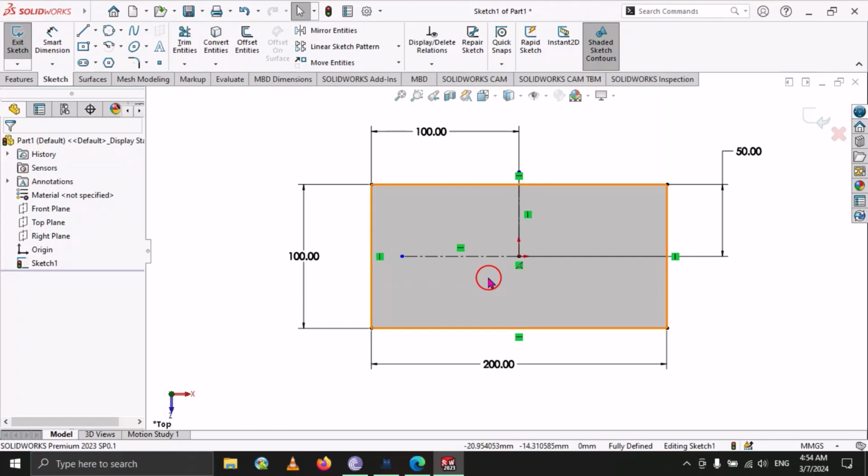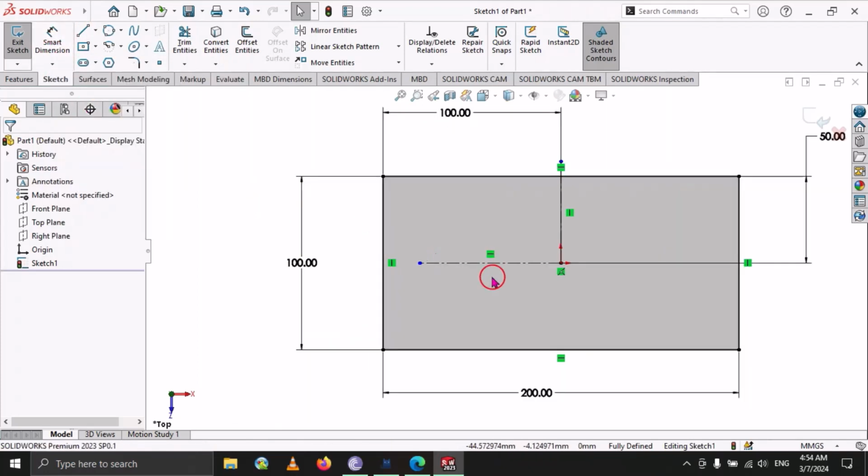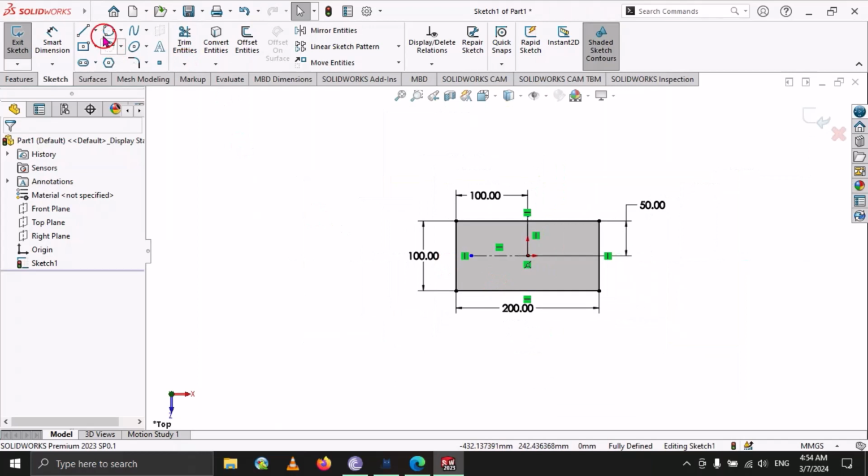First we will see the different sketch tools. We will cover these sketch tools, and then we will move to 3D. So in our initial videos we will just focus on 2D drawing. Okay, so this is the use of line. You have to remember the use of the solid line, and you also need to remember the smart dimensions. Next is the center line. I already told you that we can use it as a reference.